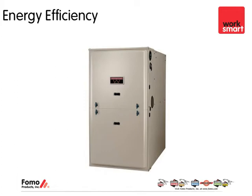A smaller furnace means a lower investment, and it means that the furnace is going to be able to run at peak efficiency. If a furnace is continually cycling on and off and never getting a chance to hit its efficiency state, your 95% energy efficient furnace may be running at 75 to 80% just because that furnace isn't working properly within the home. So the consideration of the type of furnace you want in a home really has to be tied very heavily to how tight the home and the building are.